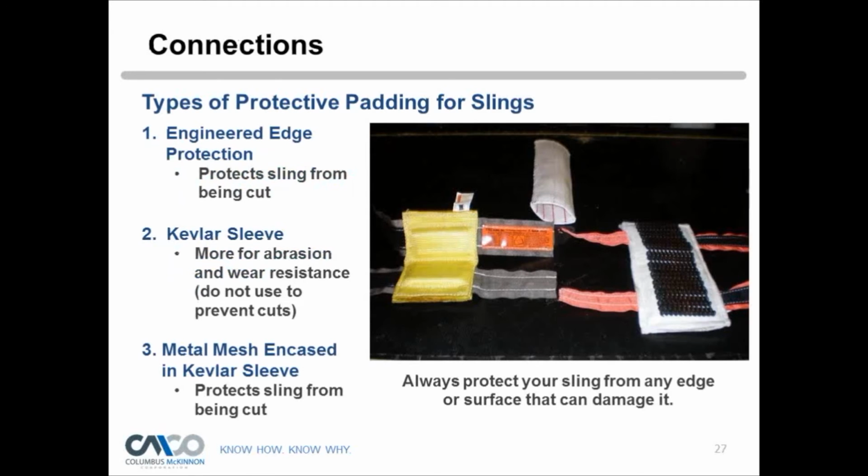Peter, one question's come in that applies to this slide, and the question is, how come only three of 4 legs take the load? Just based on tolerances of the chain, things of that nature. Some of the times 4 will take it, but most of the time we can guarantee 3 will take the load. So we don't want to overload the sling, and so it's a more conservative approach.